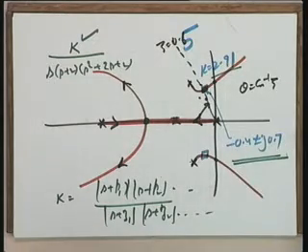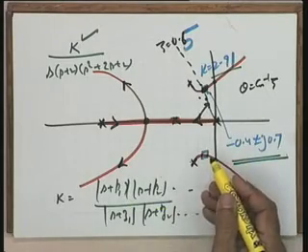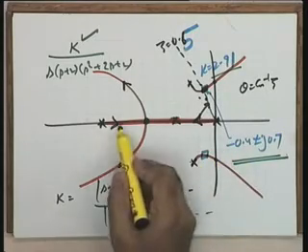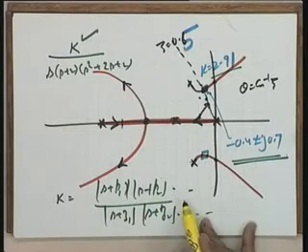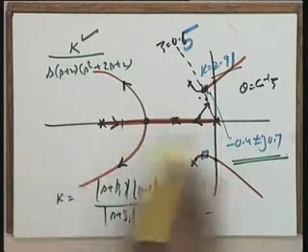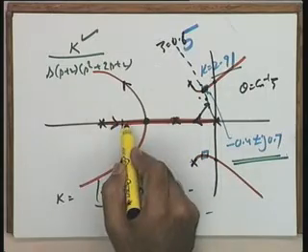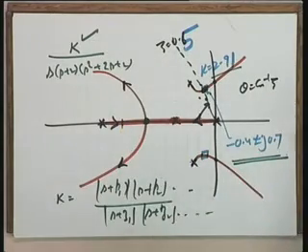You want 2 points on these two branches which correspond to k equal to 2.91. Using a computer you will immediately do it, but by graphical methods it's trial and error. You can take a point over here, apply the angle criterion or the magnitude criterion on this point and calculate the value of k, and by trial and error find a point which roughly gives you k equal to 2.91.